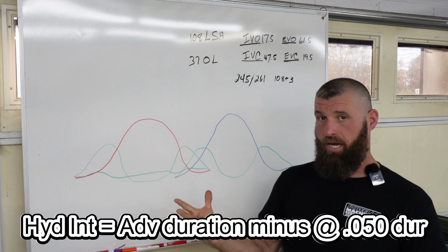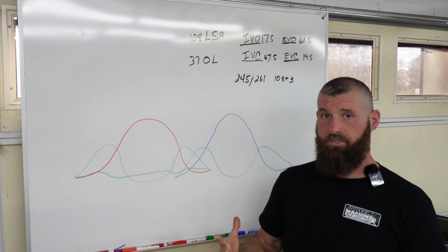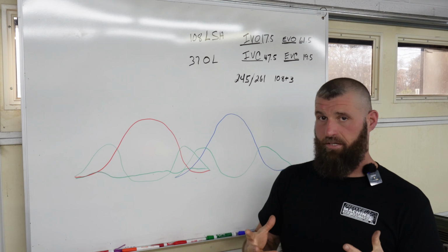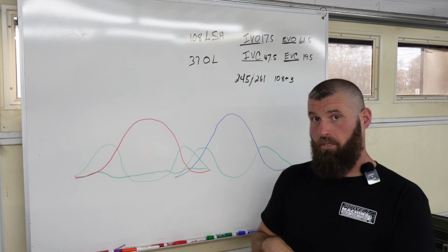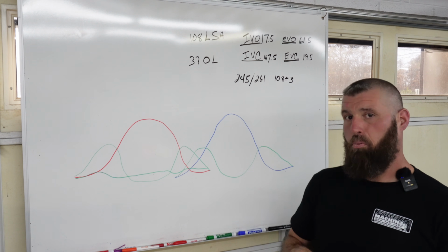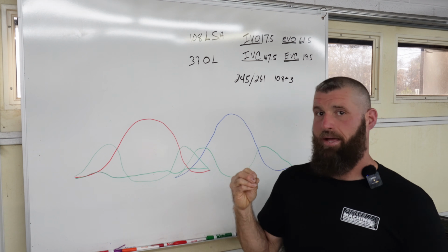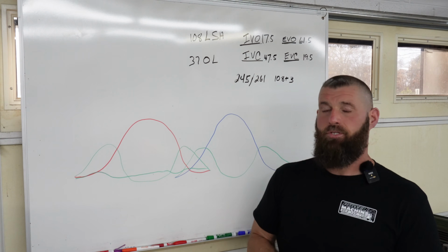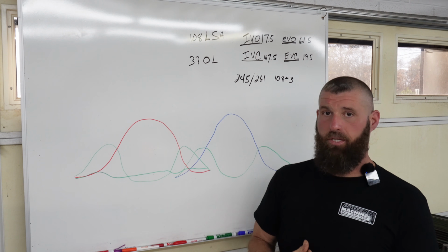And he got shaft rockers, and if he's got a nice stiff push rod, 11/32, 3/8, something like that, and the valve springs are applicable, titanium retainers, that kind of stuff, we could probably squeeze that hydraulic intensity down to 52, 53, give or take.